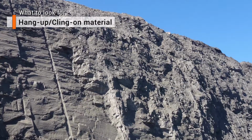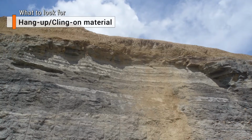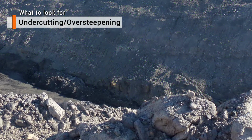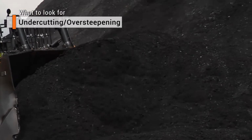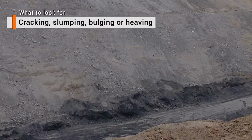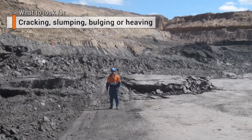Hang up or cling on material in front of pre-split barrels or above previously failed sections of slope. Visible undercutting or over-steepening of an excavated or dumped slope. Undercutting is particularly critical for identifying the potential of failure in coal stockpiles. And cracking, slumping, bulging or heaving in the face behind crests or at the base of excavated or dumped slopes.